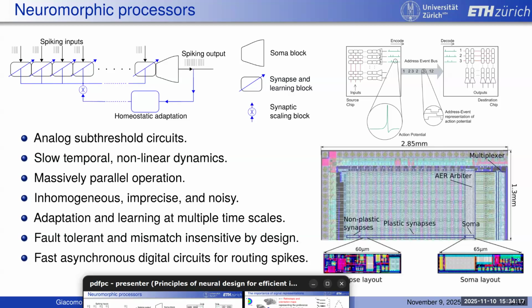And what we do is we create the layout of the circuit, and then we copy paste it as many times as we can. And the same for the synapse. The synapses also are not just multipliers like you would have in a deep network. They actually have their own temporal dynamics, and they have their own nonlinearities. If they're short-term depressing synapses, the weight changes with every spike.